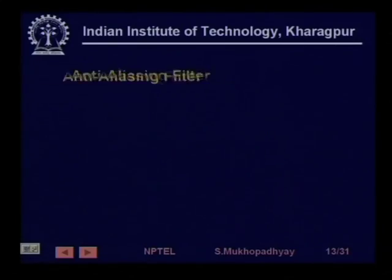So, to make sure that you do not get low frequency errors, you put a filter whose cutoff frequency ensures that you have no frequencies beyond, let us say, 1/10 of the sampling frequency. So, the sampling frequency is fixed, but you put a filter which is called the anti-aliasing filter, which will ensure that only those frequencies which are less than 1/10 of the sampling frequency are going to go through and appear at the input of the AD converter, the others are going to get blocked, so that they cannot create any low frequency error, right. Okay.